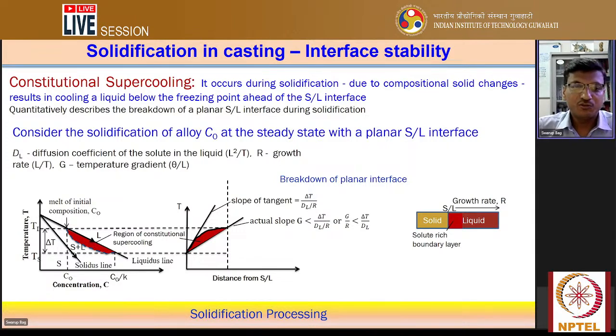So constitutional supercooling means that during the solidification, due to compositional changes, the liquid is cooled below the freezing point ahead of the solid-liquid interface. So some compositional changes occur during the solidification process. I already mentioned that we're starting from the liquidus temperature,